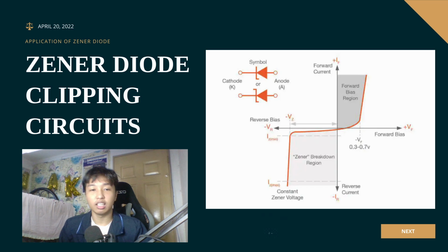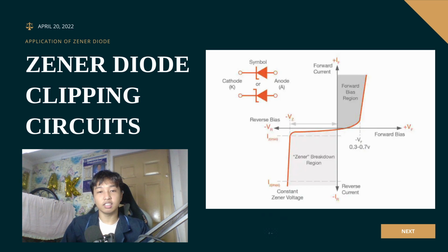Next, negative diode clipper. In this case, the reverse is true. The diode is forward driven during the negative half cycle of the sinusoidal waveform, limiting or clipping it to 0.7 volts while letting the positive half cycle pass unmodified. Negative clipper circuits are so named because the diode limits the input voltage's negative half cycle.